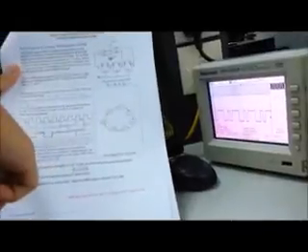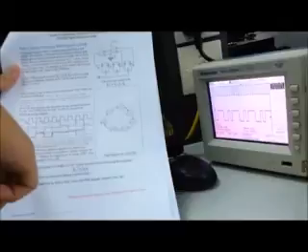And now we want to observe the sequence of X0 using oscilloscopes, whether the pseudo-random bit sequence appears random or not. So using the same circuits, we want to see the waveforms of the X0. As you can see, this is the waveform that we get using oscilloscopes. So it does not appear random.